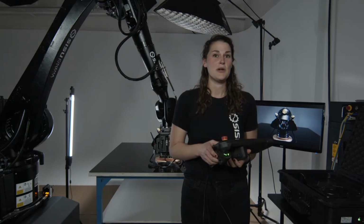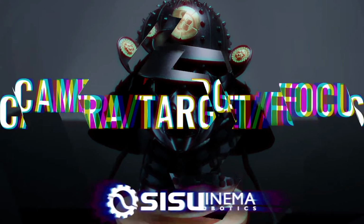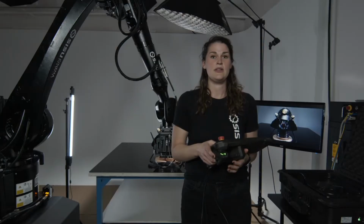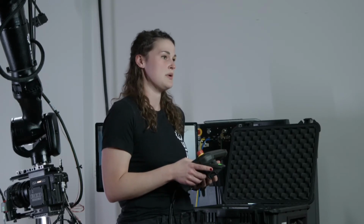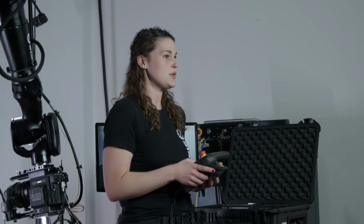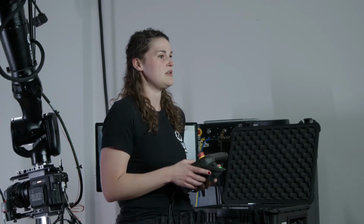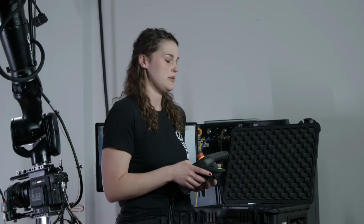In this video, we're going to talk about using the camera, target, and focus channels in your Sisu Lab program. In Sisu Lab 3.0 and later, you are able to use the camera, target, and focus channels together in your Sisu Lab program. The camera channel will control the position of the camera on your robot arm. The target channel will control what is centered in frame for your program, and the focus channel will control the focus motor and what you are focusing on for that program.